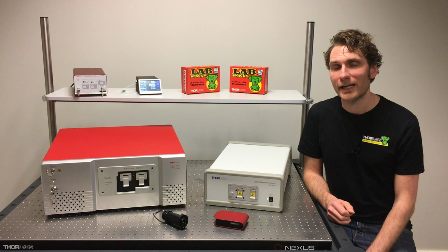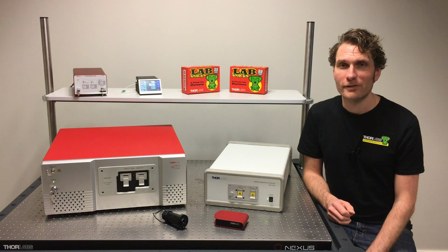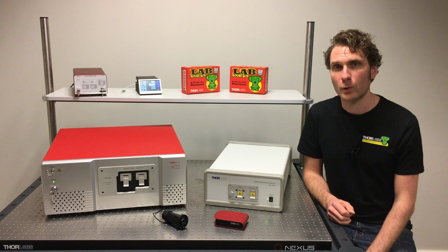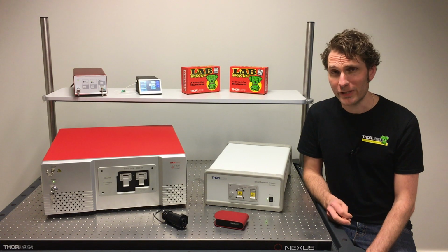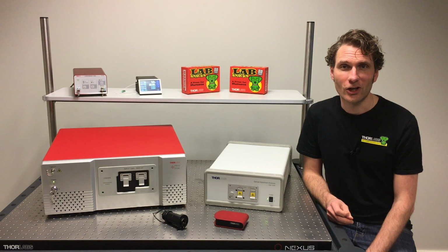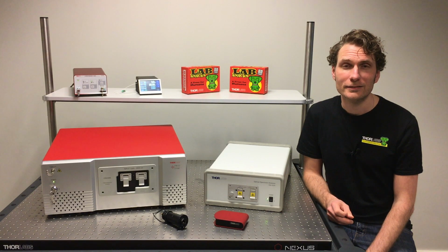But the Redstone has 4 times the resolution of the OSA 20X. It also has 2 detectors, allowing for a wider wavelength range with the Redstone, and a good sensitivity. And the free space input port of the Redstone is larger, so it collects more light and can detect weaker sources than the OSA 20X.